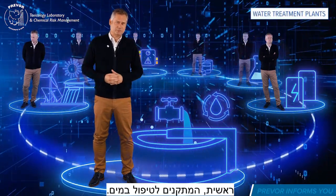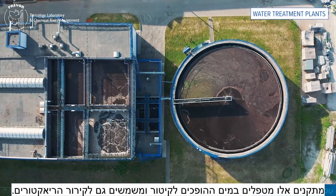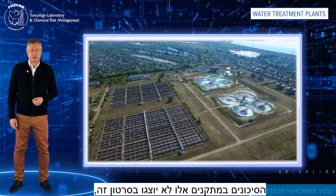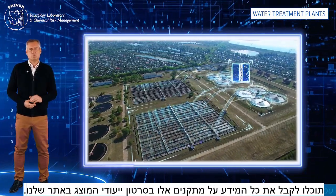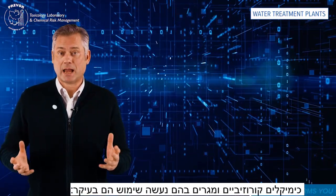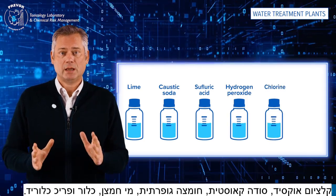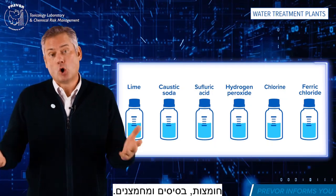First, the water treatment plants. They prepare the water that will then be transformed into steam, as well as the water used to cool the reactors. The risks of these stations will not be detailed in this video. You can find all the necessary information in the specific video on water treatment stations. Corrosive and irritating products are mainly lime, caustic soda, sulfuric acid, hydrogen peroxide, chlorine, and ferric chloride. So these are acids, bases, or oxidants.